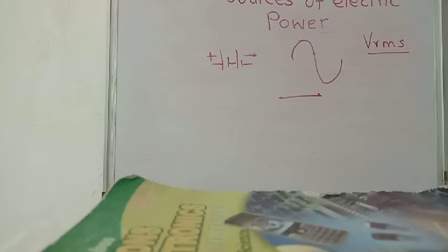generates DC voltage. So when the shaft rotates, then it cuts the magnetic field of the magnet. Therefore, it produces change in magnetic field or change in magnetic flux, and due to change in magnetic flux, DC voltage is generated across the coil.